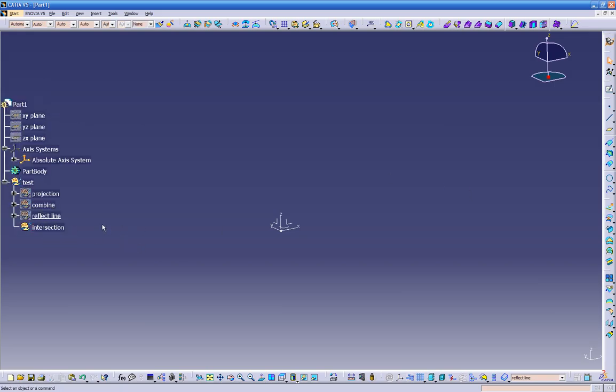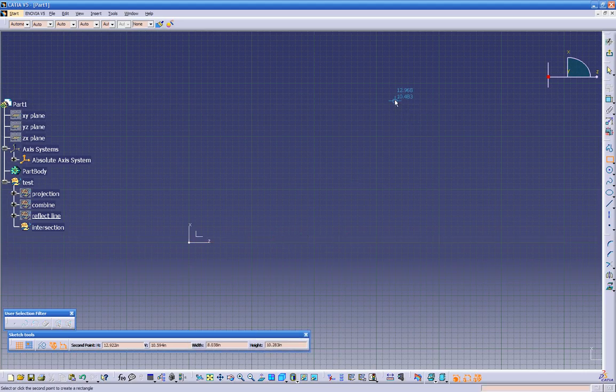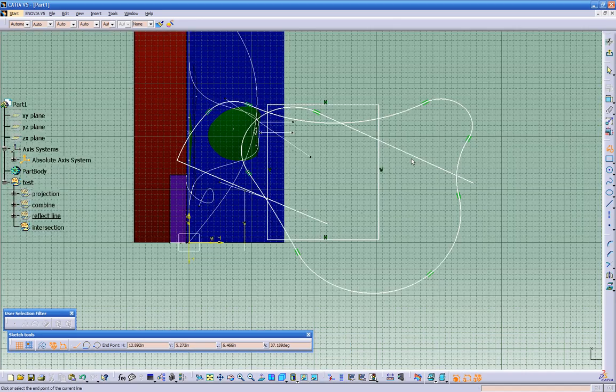Let's make this the default, because right now if we try to build a sketch, for example, and we try to make a rectangle, we don't see it, right? We try to create a profile and we can't see it. It's like, hey, what's going on? The reason we can't see it is because this is the default and it's already turned off. So right now everything that we're building goes into this folder at the no-show level. So if I go to swap visible space, there we go. This is all what I'm creating right now. Because this is turned off, everything that I'm working on right now goes into this level.